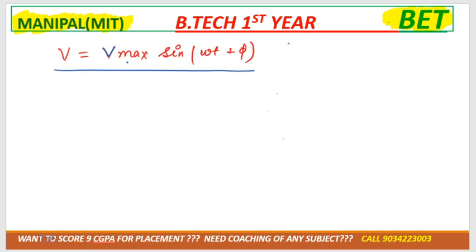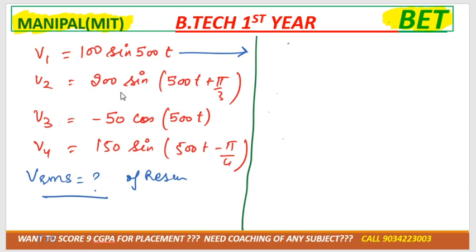V is the voltage, V max is the maximum voltage, since it is in sinusoidal form, omega t is the angular frequency term, phi is the angle. Correct? So here this is standard, this is sine, and this is also standard, but this one is in the form of cos, so that is not standard. Now for this particular case we need to convert it into the standard form. Minus 50 as it is, the cos we need to convert into the form of sine, so that would be sine of 500t plus 90 degree. If a cos form is given, if we add 90 degree to it, then we get the sine form. Okay, clear till here?